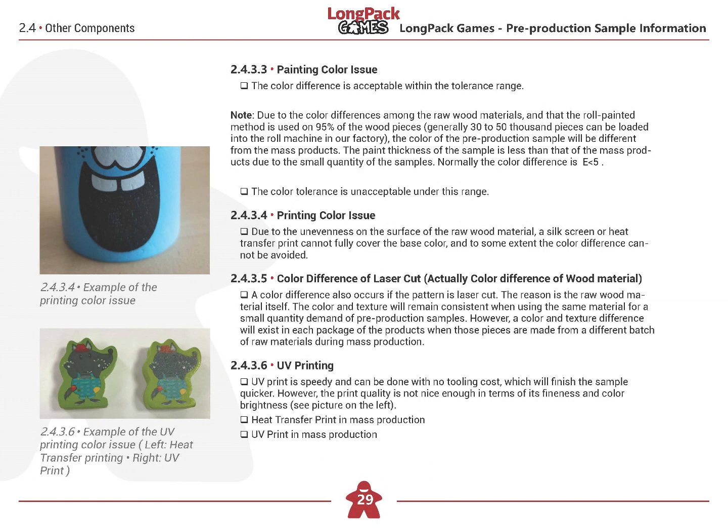The paint thickness of the sample is less than that of the mass products due to the small quantity of the samples. Normally, the color difference is ΔE less than 5. The color tolerance is unacceptable beyond this range.